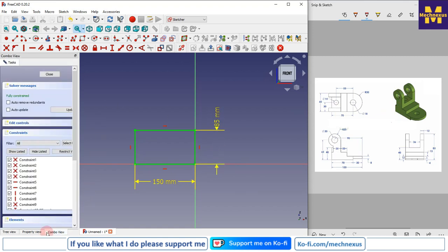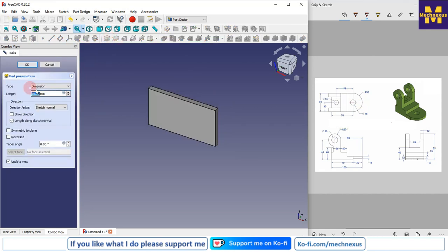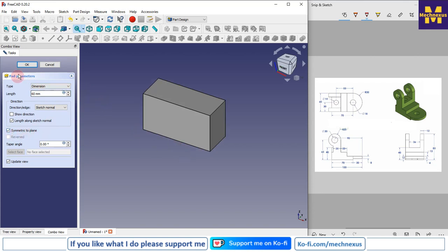Now I will come out of the sketch, and total extrusion is, this is the radius R30, so total it would be 60. So I will give the pad and give it 60, and never forget to make it symmetric to the plane.